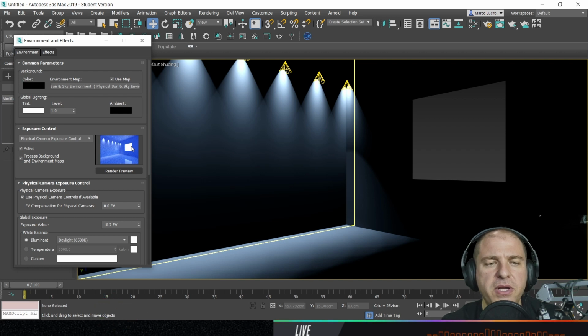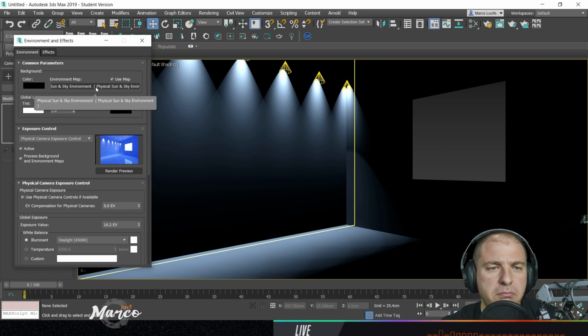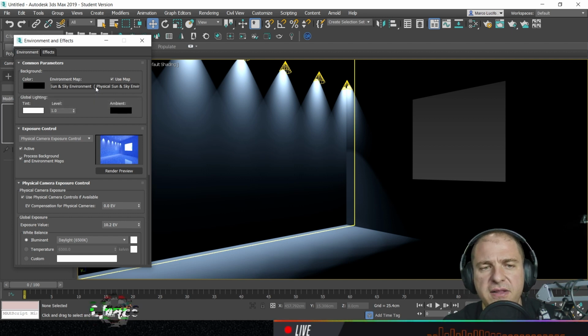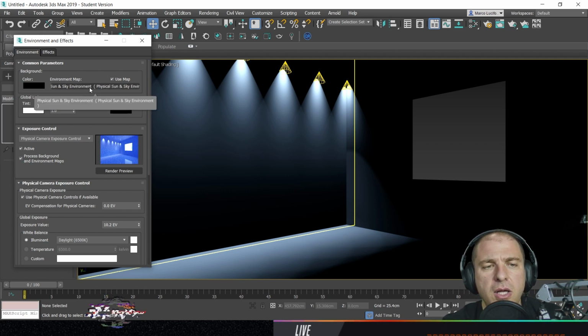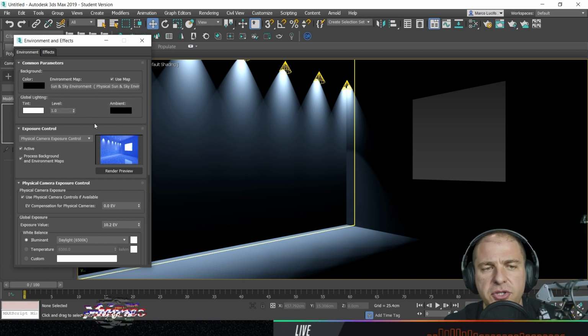This is happening simply because when we create our sun positioner, we automatically add something called the sky map on the environment parameter, and this is true for basically all render engines that we use. So this is true even if we are not just using ART renderer, but even if we use V-Ray or Corona render. So basically we need to manually get rid of this additional map.